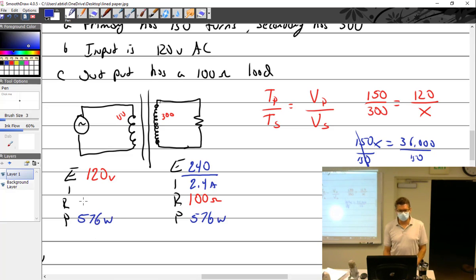576 watts. So now using that, which is P=IE, I want to know the I. So it's P, power, 576 divided by 120 should equal 4.8, which is twice that, 4.8 amps. So 120 to 240, basically because it's a 2-to-1 ratio, there's twice as many in the primary as there is in the secondary. This is really times 2 this way and times 2 that way, and this is equal. So the wattage stays the same throughout the transformer. That's the power. The power stays the same.